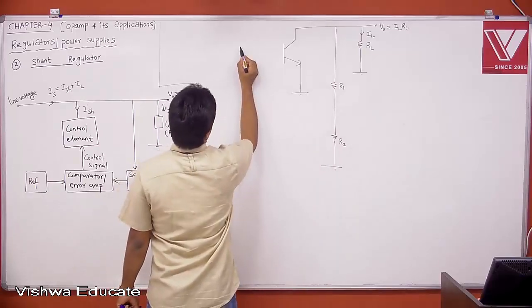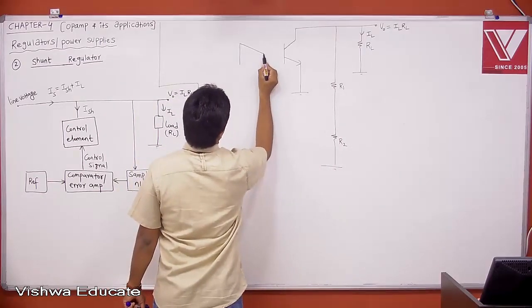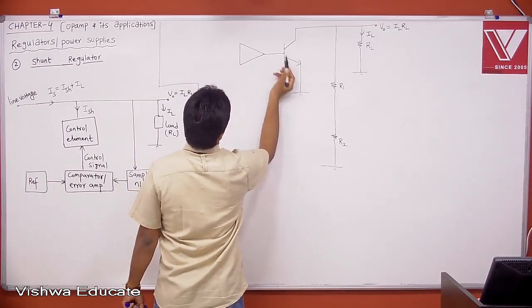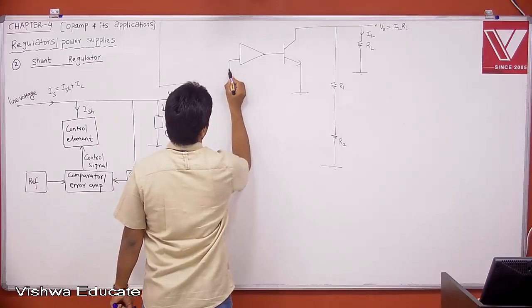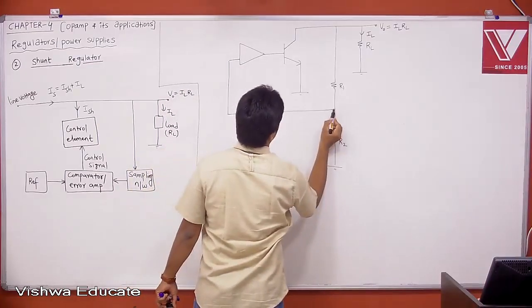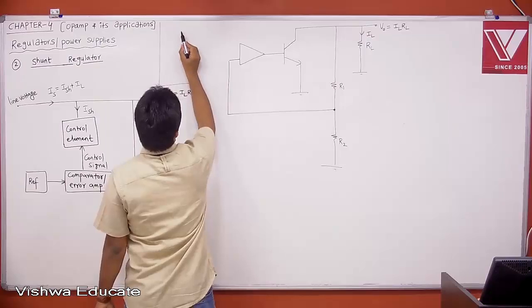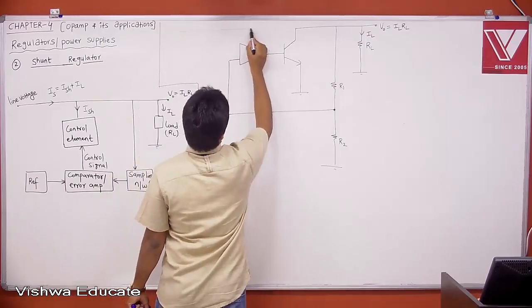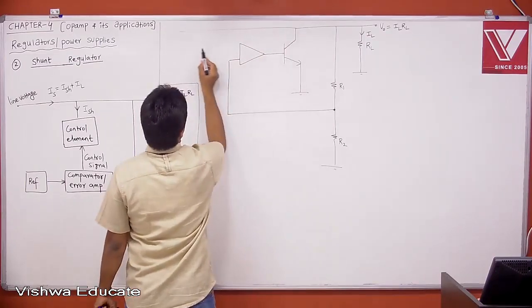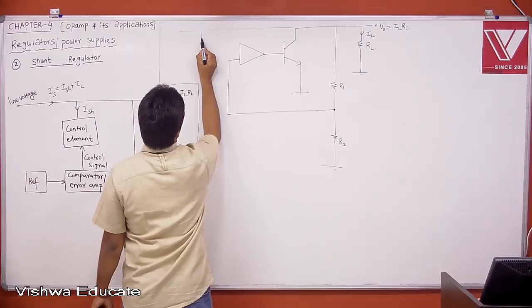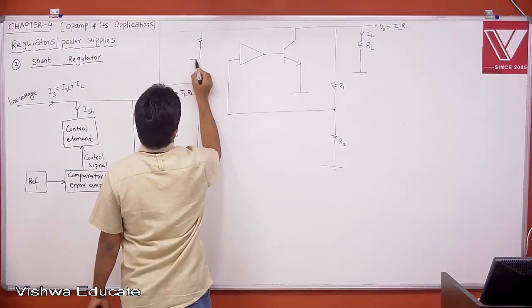Then here this is going to have the error voltage or error amplifier. Then the sampling voltage will be coming from R1, R2 combination. Then this is our line voltage, right? Then the reference, whatever reference, typically I told you, right, you can use Zener diode.